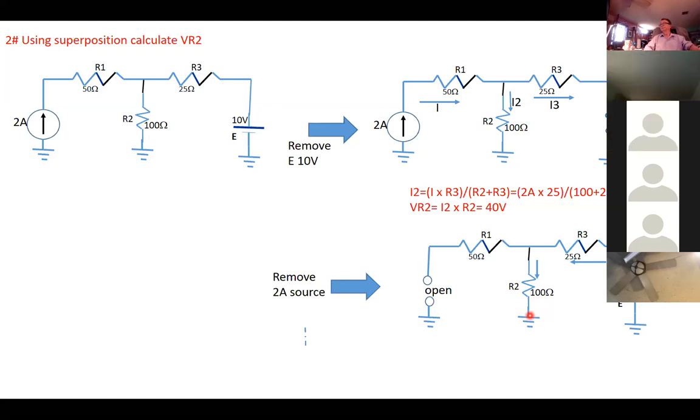Voltage divider? Exactly. That's what I wanted. Voltage divider. You take 10 times R2 divide R2 plus R3. You do nothing with R1.